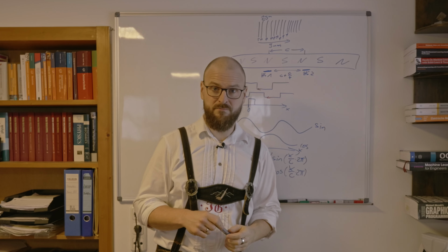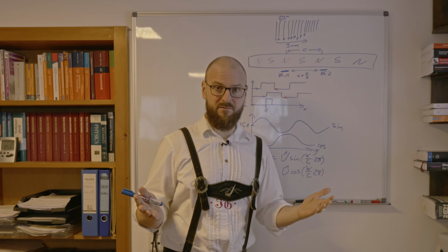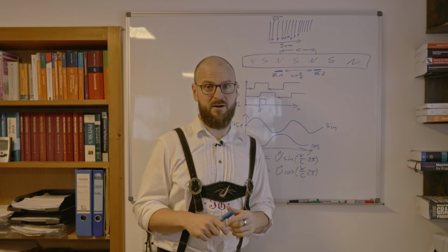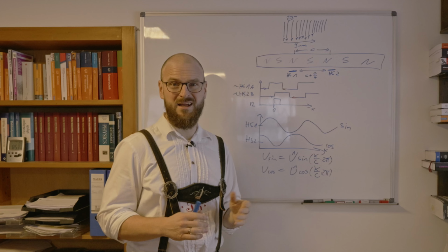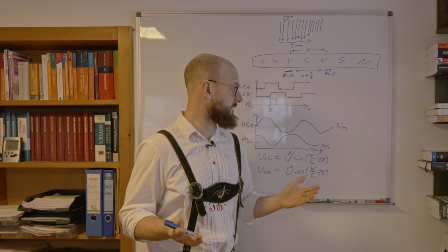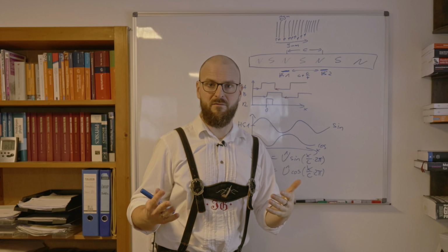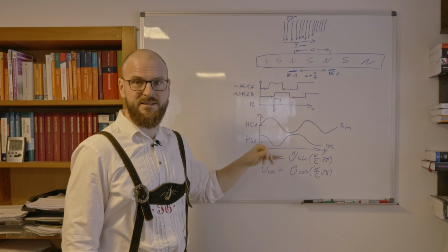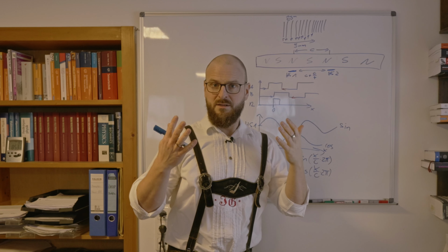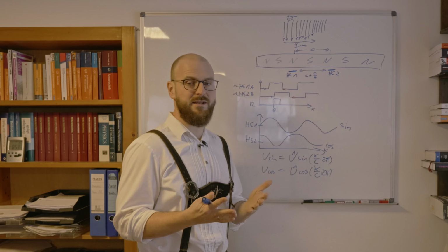And moreover, we can just filter non-sine function parts and non-cosine function parts out of the sensor signal. That's no problem. We have filter options for frequencies, and so we know the frequency of our period and we can filter for that. So the assumption that this is a usable sine or cosine function is very well defined.